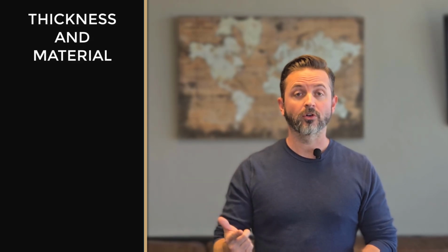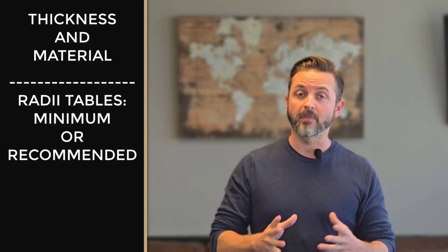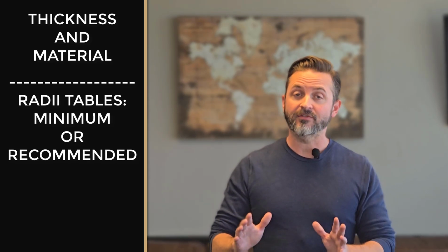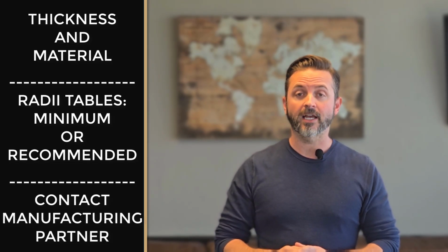In summary, the two main factors that affect the inside bend radius of your sheet metal or plate form designs are its thickness and the material of construction. Inside bend radii tables can be defined in the form of minimum or recommended for various alloys and heat treatments. If needed, reach out to your internal or external manufacturing partner for inside bend radii that they most commonly use.